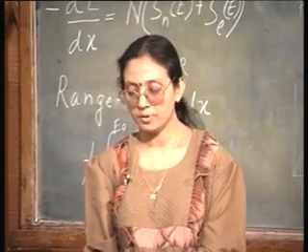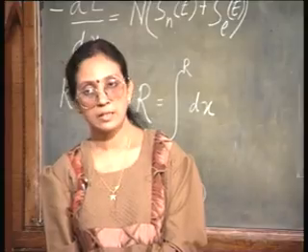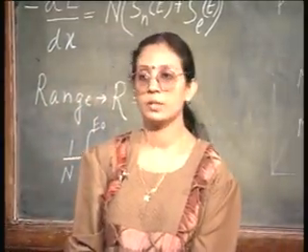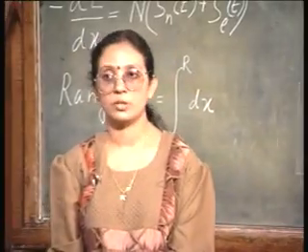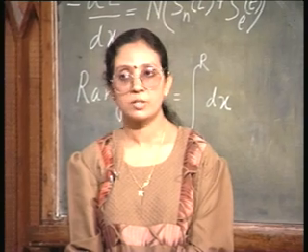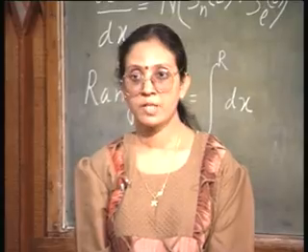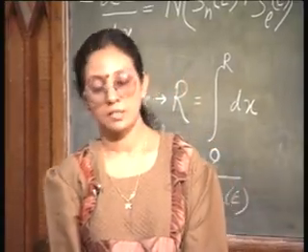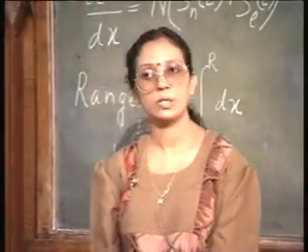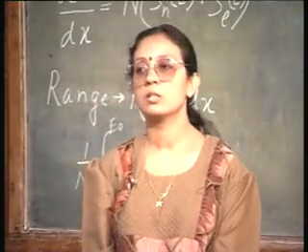Just to give you an example, the critical energies below which the nuclear stopping dominates and above which the electronic stopping dominates, these are also different for different incident ions. So, for silicon, this critical energy, for boron it is 15 kilo electron volt, for phosphorus it is 150 kilo electron volt.